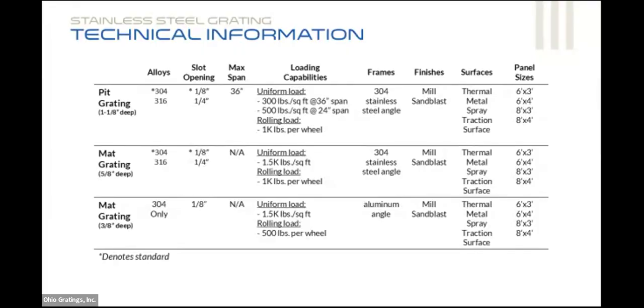And then from a material depth standpoint, what's typically seen in specifications is 1 1/8 deep material, but there's other depth options as well, just depending on the area that you have designed, which would be 5/8 deep or 3/8 of an inch deep in different applications. Each of them have their own specific loading capabilities, so it's just something that you'll want to pay attention to with your design.